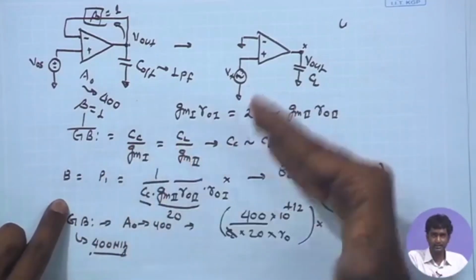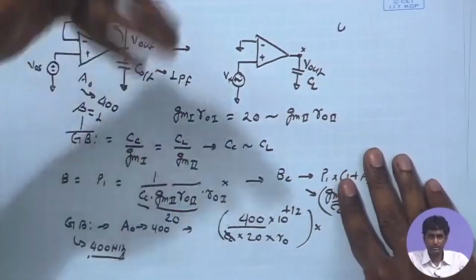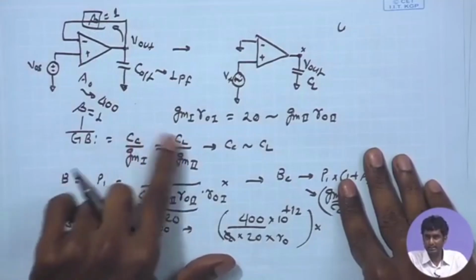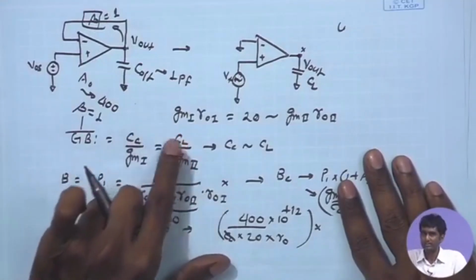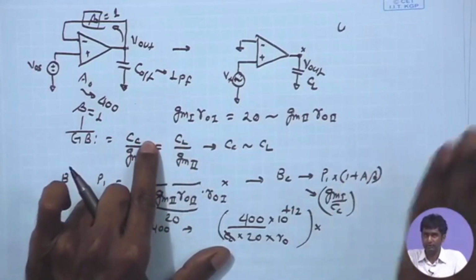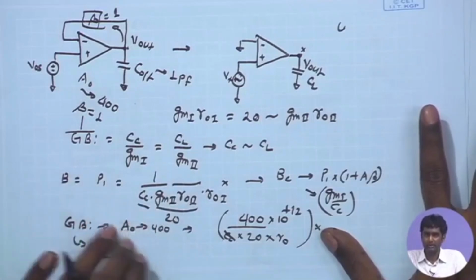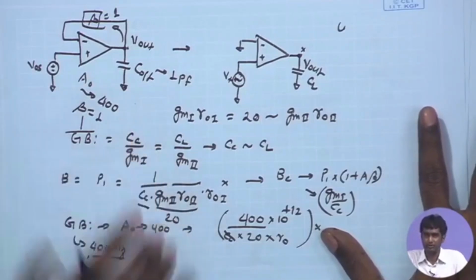Cc and Cl are getting determined by the constraint on the sampling capacitor. We want it to be sufficiently high so that leakage and other non-idealities do not affect it. That is determining a large magnitude for the Cl and hence Cc for 45-degree phase margin. Once the Cc is known, the bandwidth is going to be determined by the Cc and the GM-R of the first stage.